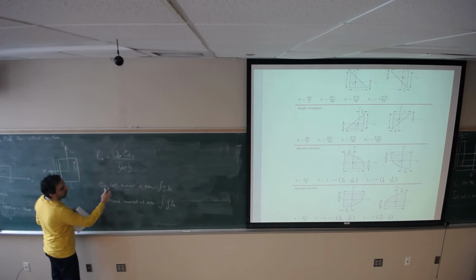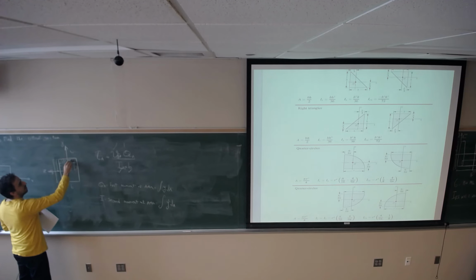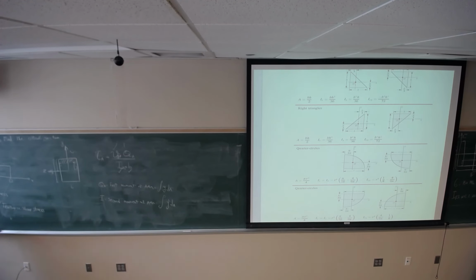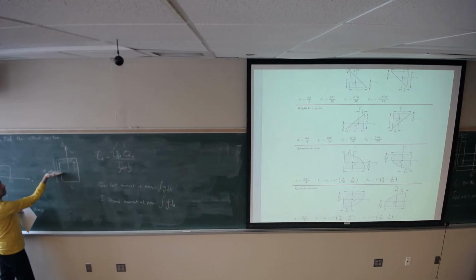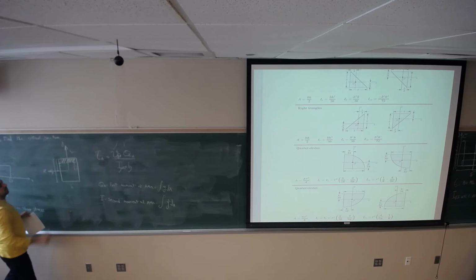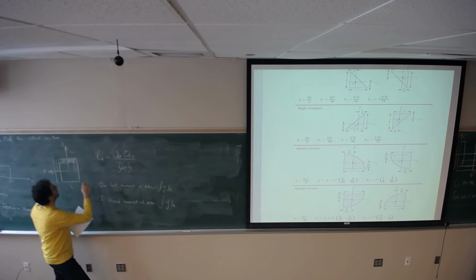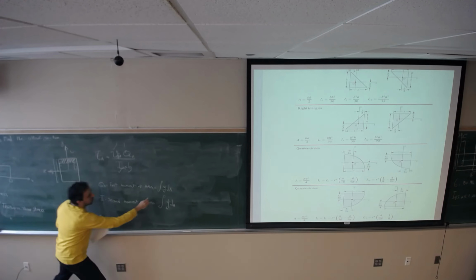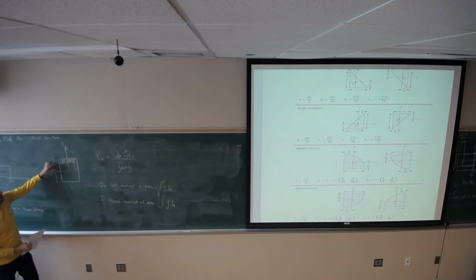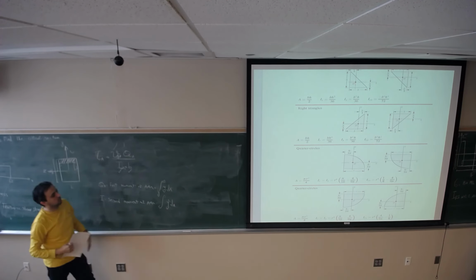We need to find the first moment of area on the top of point A. So I draw a line parallel to the z-axis and do the integration of the area for this part of the cross section. Y dA means the integration from y to C, from this point to this point. Whatever the area is between these points should be covered.